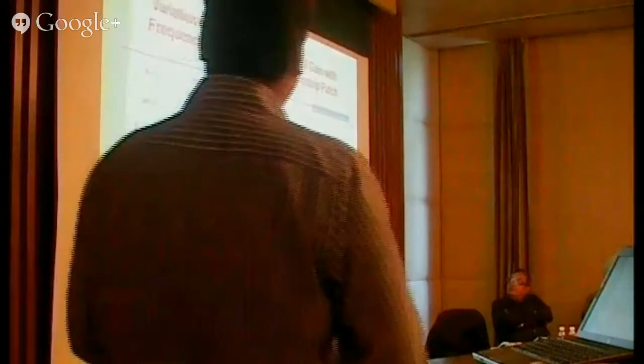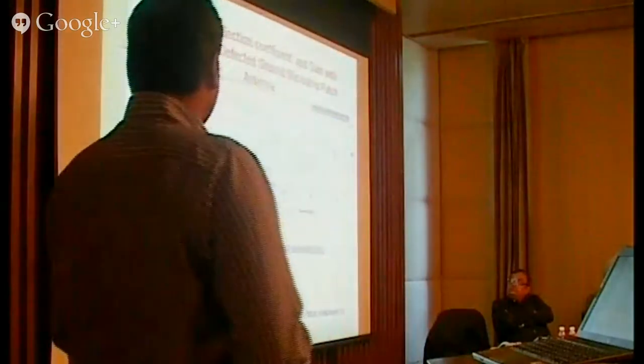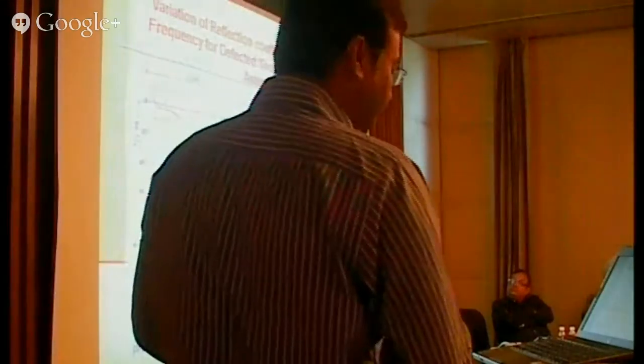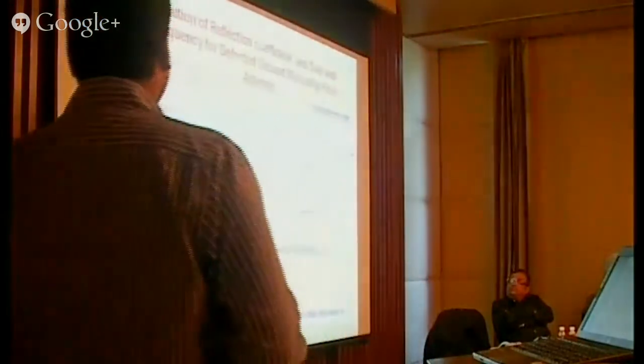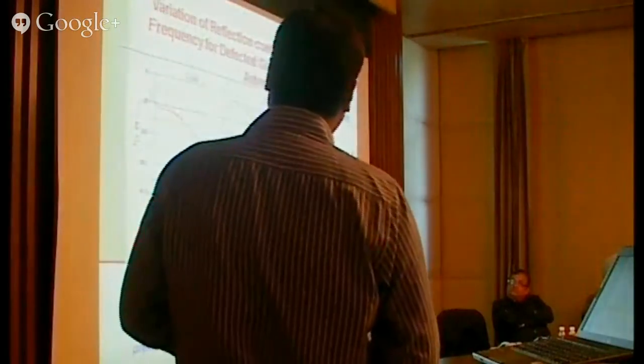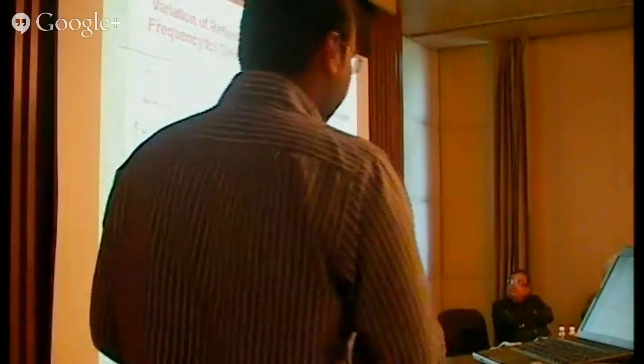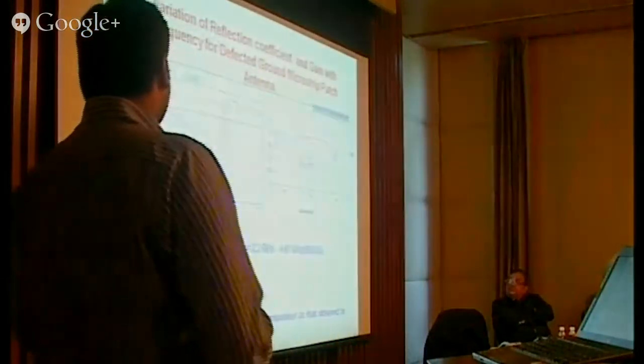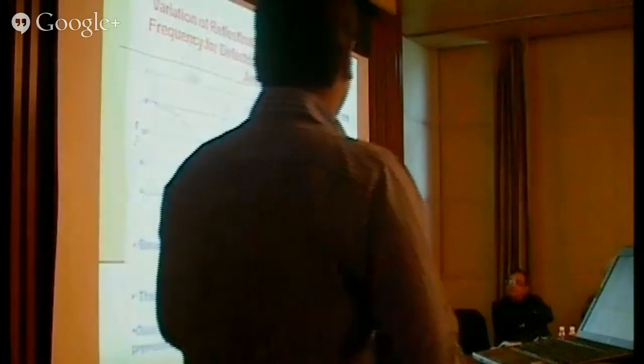The result of S11 and gain with frequency. First, S11 shows a broadband impedance bandwidth from 2.2 GHz to 4.47 GHz, almost 69.63%. The gain is nearly 2.2 dBi, and gain is improved considerably in comparison to that obtained in the previous case.